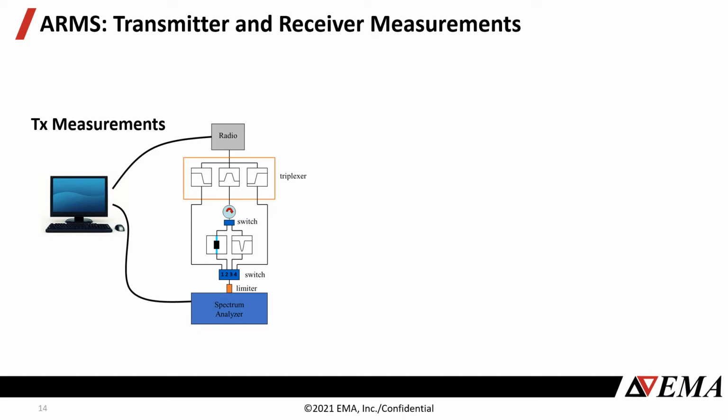The band pass signal goes through the stage here in the middle, and in one case, we're very accurately measuring the fundamental of the transmitter. And in the other case, we're suppressing the fundamental with a notch filter, which allows us to measure the performance of the transmitter close to the fundamental, but not at the fundamental.